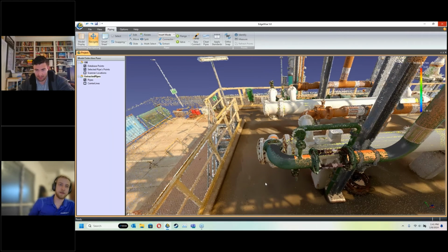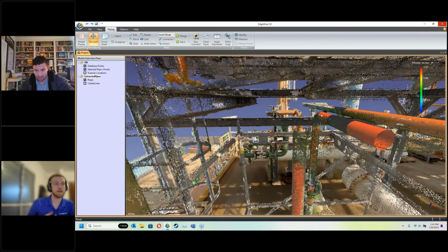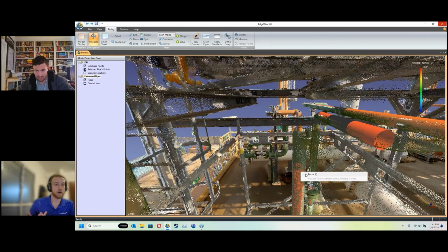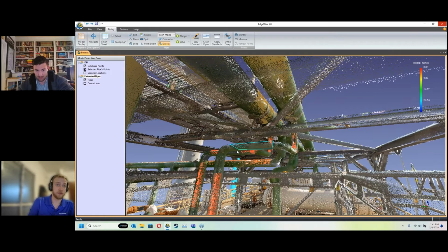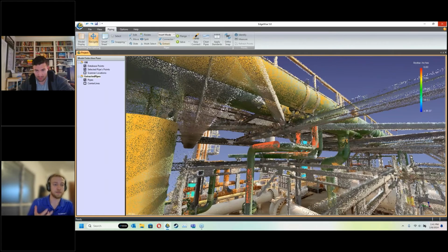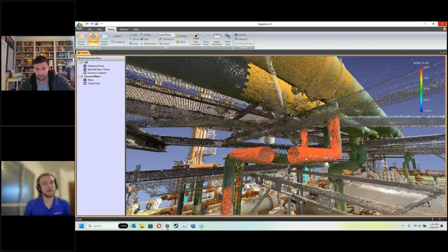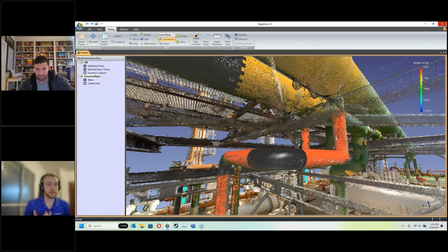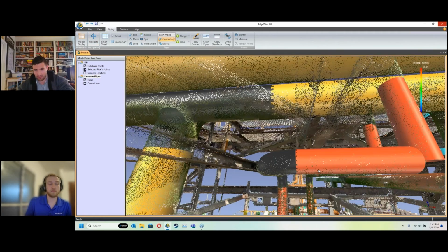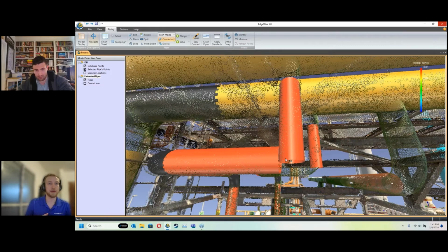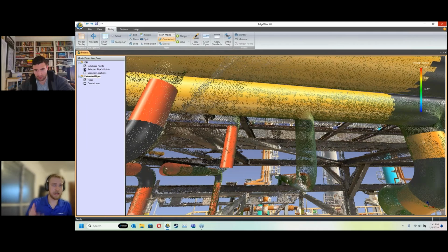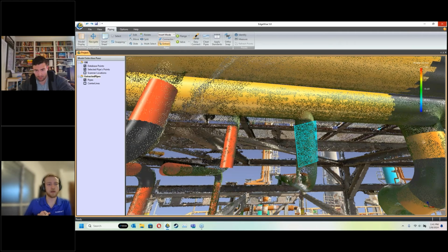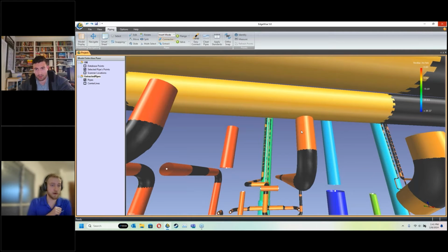And so the key here is point cloud density. That's really the biggest factor. In a lot of scenarios with point cloud noise, if it's noisy data, we're going to struggle to push stuff out. And that's what's so impressive about the VLX and its ability to have such crisp data: there's really low noise. It's good coverage because it's mobile, and so you can walk around and you get lots of coverage very quickly. And they do a very good job of taking that coverage and balancing it out across the elements. So we get great coverage, which is one part, and we get good, consistent density.